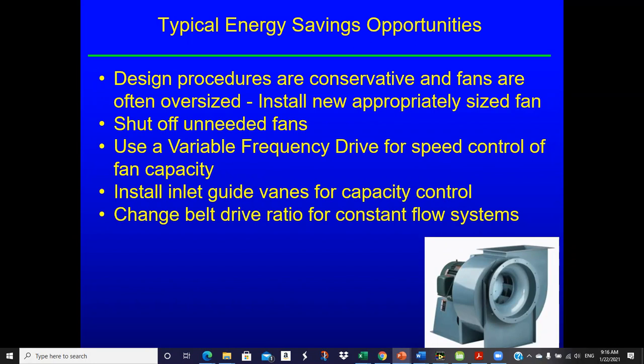The contractors, when they go to purchase that thing, say, well, he called for this one, I'm going to go up a little bit, I'm going to put in one that's a little bit bigger, etc. Oftentimes when you turn the thing on, holy moly, we're looking for 10,000 CFM and we've got 17. Well, no problem. We'll just pinch the dampers. And that works. You got your 10,000 CFM. Everything runs. Everybody's happy, except the guy paying the utility bill.